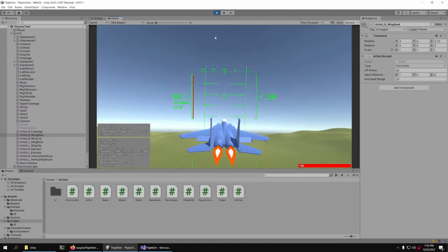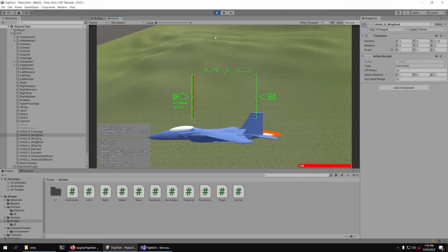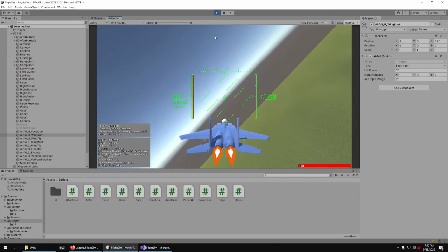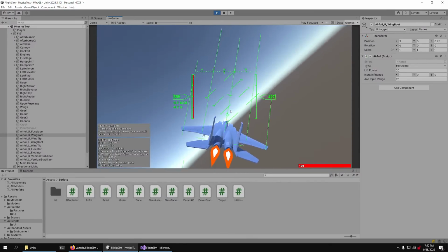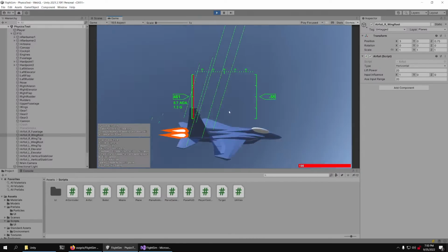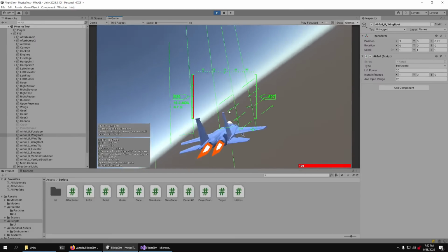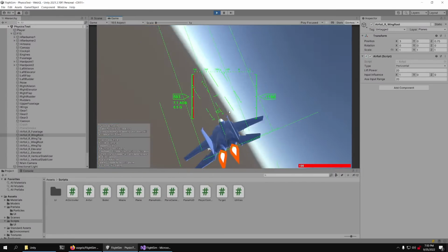And there's some crazy oscillations from the stability right now. So the horizontal stabilizers provide stability, which means they want the bore sight and the velocity to match. It's trying to bring the nose of the plane to match where the velocity is pointing. The problem is that it's going to cause you to pitch down, which is why we have a very strong pitching down movement.